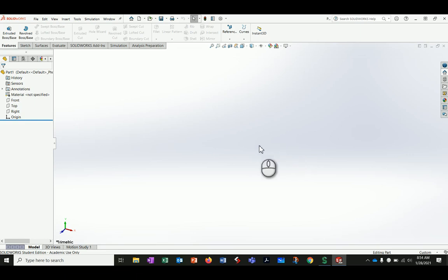Hello. So what I'm going to talk about today is surfaces. And surfaces are a non-existent entity in the sense that they're zero thickness. Surfaces are really useful in SolidWorks because, when it's calculating particularly quite organic shapes, it doesn't have to worry about thickness, and that makes the calculations, as you can imagine, way simpler.